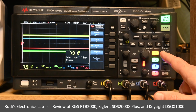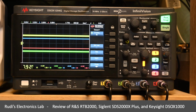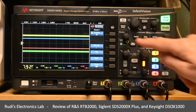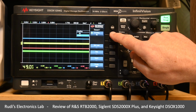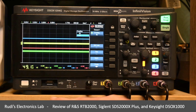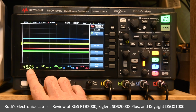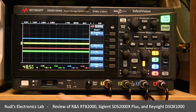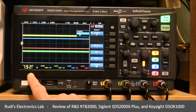Now what happens if we actually couple the channel to AC, then the menu disappears. This is a thing with the Keysight, sorry, that these menus disappear all the time when they're not activated. Now I change my channel to AC coupling, and I see it going down here. And what happens here, very nice, the meter automatically changes to AC because it realizes that a DC measurement is actually not possible. And the moment I return my channel to DC, the meter jumps back to DC.